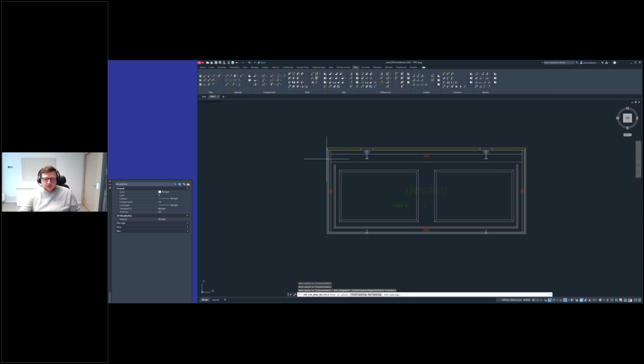Then I want to align it to the center. And between the custom materials, I want to have maximum spacing, so I will use as much as I can. The spacing should be 800. And I want to have an offset from the starting point of 400 and from the end point also 400. And they're added like this.